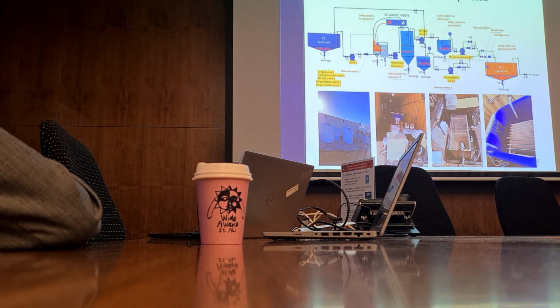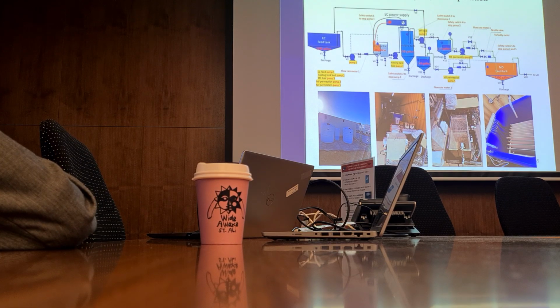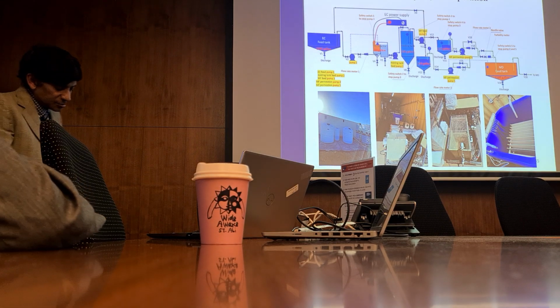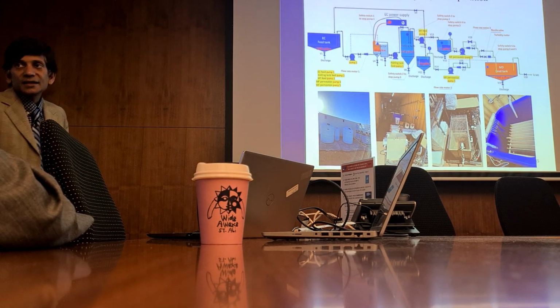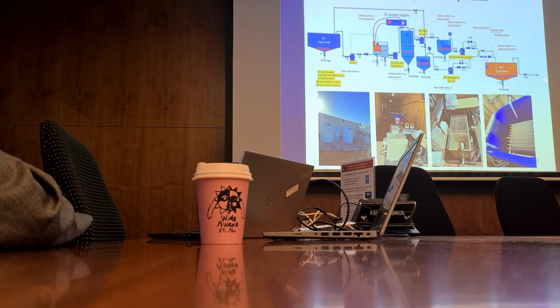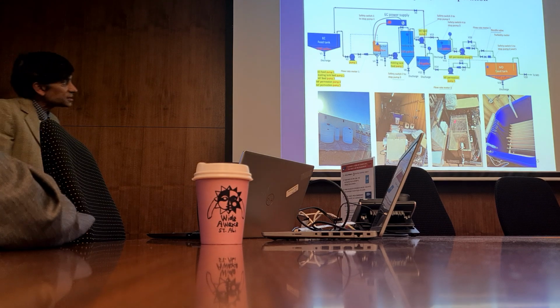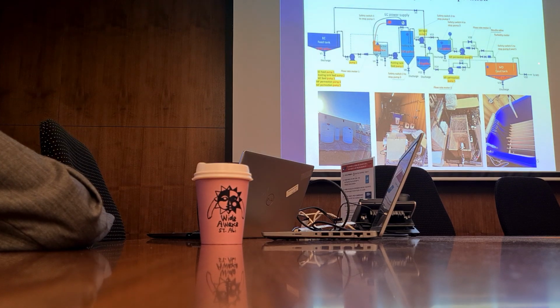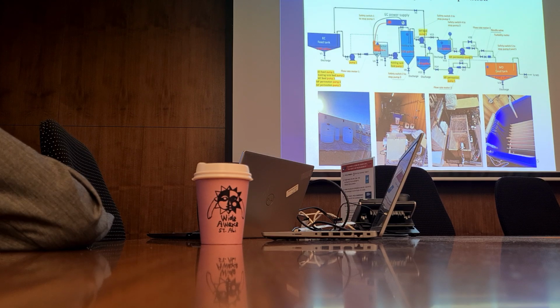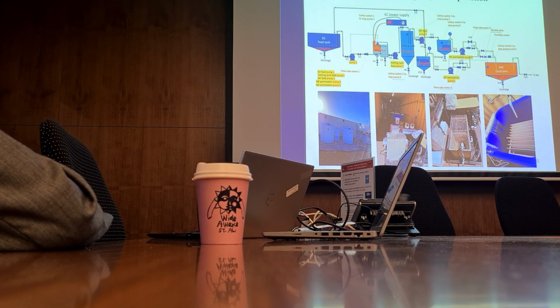So no wetting. How long did you operate this? One week was the test. Now the system is all at Texas Tech, and they may be running it more, I don't know. But the test that we ran was for 5 days. It's not truly a continuous process, because we'd run our EC process, and then collect water in the MD feed tank, and our EC ran much faster than the MD part. After about 8 hours we have to stop, replace some electrodes, clean, and so forth. The electrodes are run such that the anode and cathode are only on the 2 outer electrodes, so there's a differential rate of electrolysis occurring within the plates. But you can buy commercially available EC systems today that people are selling.